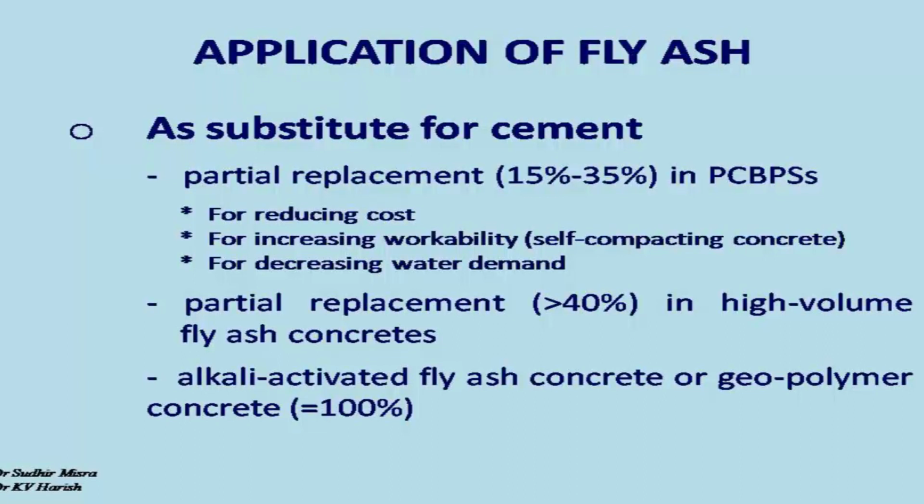However, fly ash can also be used at higher dosages, typically greater than 40%, but when you use greater than 40%, there are several problems such as setting time problems and low rate of strength gain problems, and these have to be addressed whenever you use higher dosages. Such problems have to be addressed by using other strategies, such as using accelerators or other materials in the mixture. So, typically greater than 40% is not used.